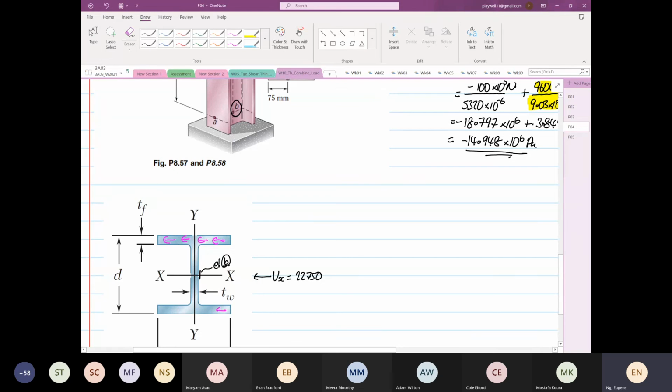So we know that this is the main flow, the web controls the flow, right? So element B is exactly down here. From the upper flange, the shear flow will be coming down this way, and the lower flange will be coming this way, right? So we're going to find again shear xz. So what was the QB for element B? Anyone?